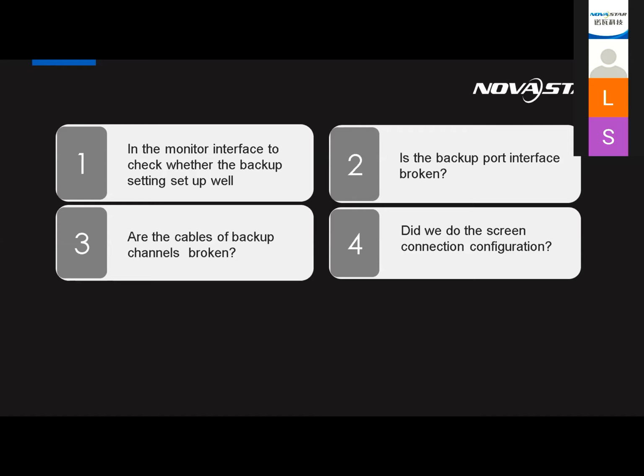The fourth one is, did you do the screen connection configuration? This is what I saw in one project. The customer asked me, Rob, why can't I get the backup to work well? And I used TeamViewer to log in. I noticed he didn't do the backup screen mapping. He thought I just need to do the primary mapping, I don't need to do the backup mapping. So that's wrong. You need to do backup mapping. So check this point.